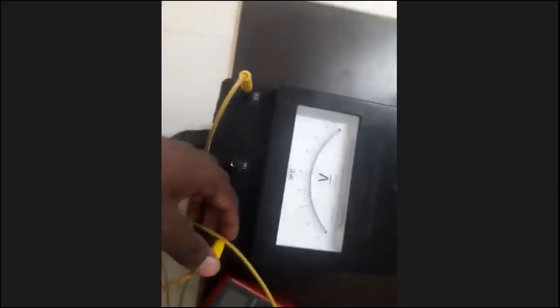To measure the supply voltage, I want to put one voltmeter across positive and negative. See, across the positive and negative terminals, I have connected a voltmeter. See here it is one of the voltmeters, connected across the positive and negative terminals. Okay, so this is the simple connection diagram to perform the no load test, or to perform only the running test.